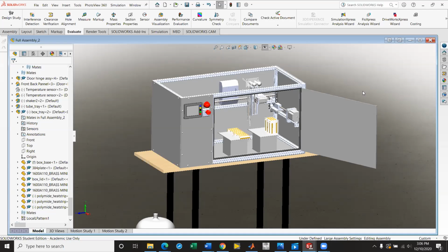I agree. The T-slot does make it great to add extra stuff onto it, but so does a bunch of 1/4-20 tapped holes on 1-inch centers, which is how every optical laboratory table, well, actually they're M6 holes on 25mm centers, is set up. It's a flat table with a bolt pattern on it. Another great way to get modularity. As an engineering designer designing a product, you get to make the call on how you want your system to be modular.